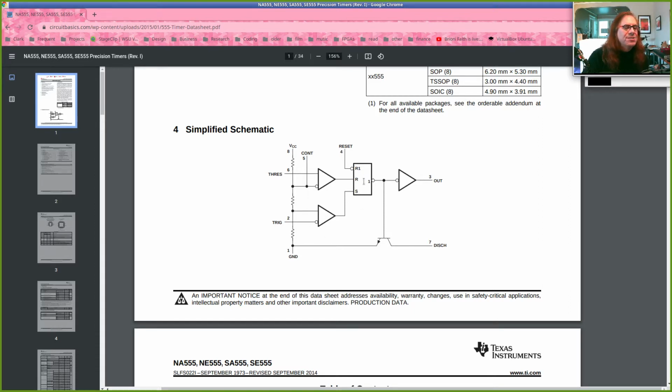An SR flip-flop, an output buffer that just protects the output from the input, and a transistor. And it's this path right here which gives you feedback. And if you have feedback, you have potential for oscillation, and that's really what this is doing. There's no crystal inside, so this is a pretty approximate way to generate a waveform.